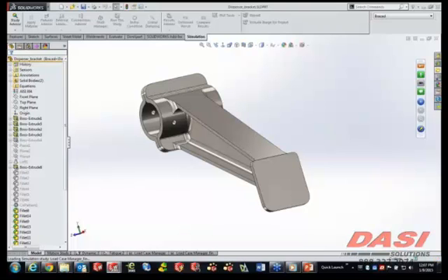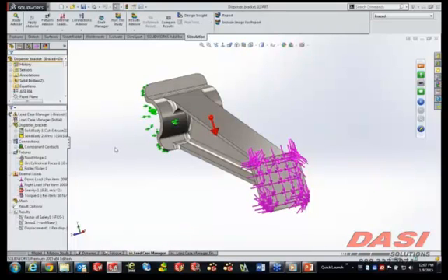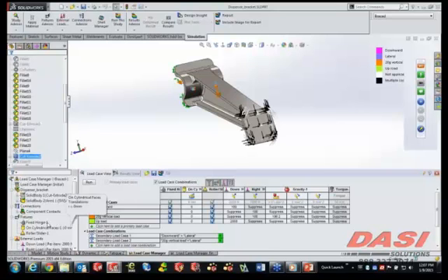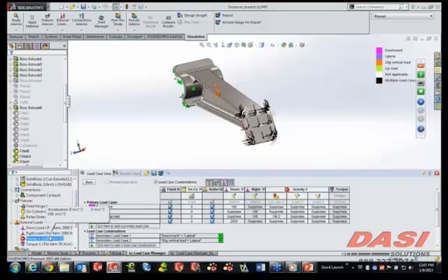So I want to show you this tool we've created called the Load Case Manager. When we look at the manager, essentially it's a tabular format for setting up different scenarios, and those scenarios can have different settings for each of the inputs. So when you're looking at things like your fixtures and loads, we've got 3 boundary conditions from fixtures, and then down here we've got 4 different loads: different directions, gravity, and torque.